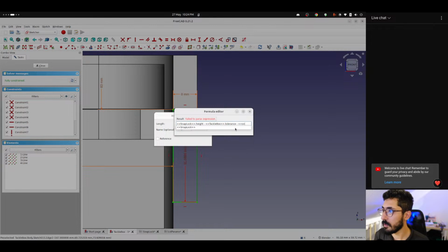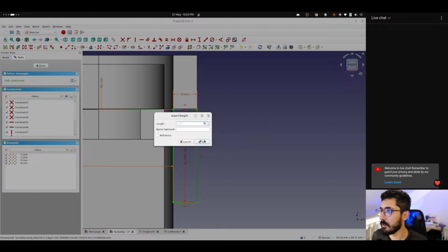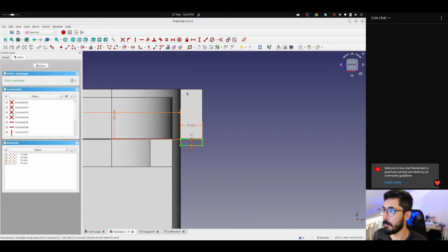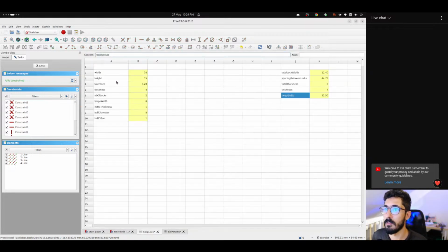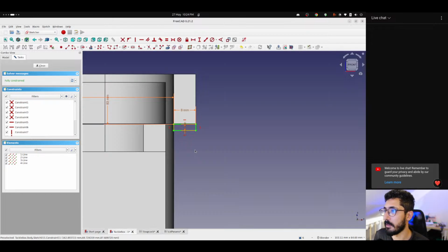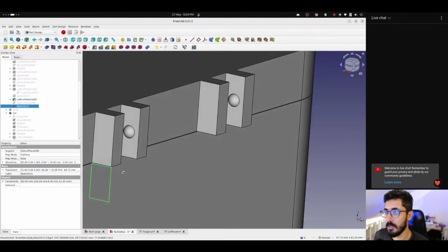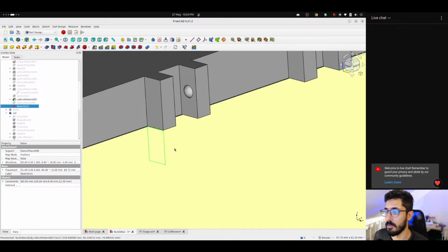Minus the snaplock dot height in lid. We end up with 2, and that's because the depth here is, so we need to increase the height. Let's do 20 or even more. Let's do 25. Now the issue with FreeCAD, the current version, is that it will not update unless I close the sketch. This is like a known issue or something.